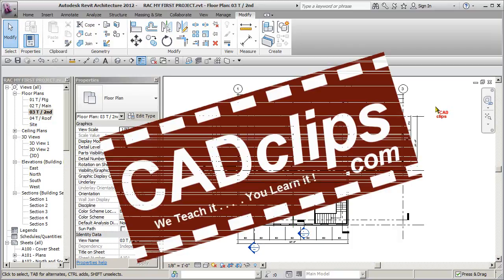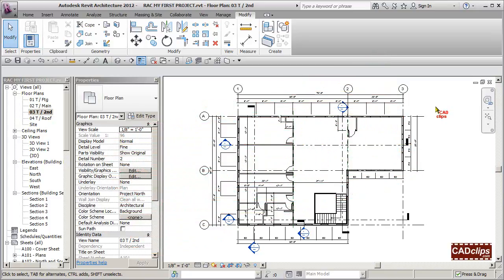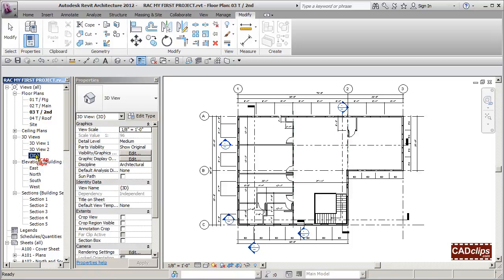And here's a fun lesson on 3D sections and plans. A lot of people don't know you can do this in Revit. So what we're going to do is create some new 3D plans based on the default 3D view. We'll duplicate them and then apply plan views and sections, etc., to those 3D views, and the effect will be really neat. It'll have a 3D sectional box.